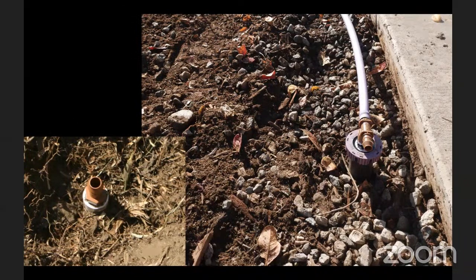If you are installing the pressure regulator and filter at your valve, you can still use all of the underground pipe from your spray system, but instead of keeping the sprinkler body, generally what you'll do is dig and access where the PVC pipe connects to the sprinkler body, and use the adapter that goes from the thread that you put thread seal tape on and screw in where your sprinkler screwed in.